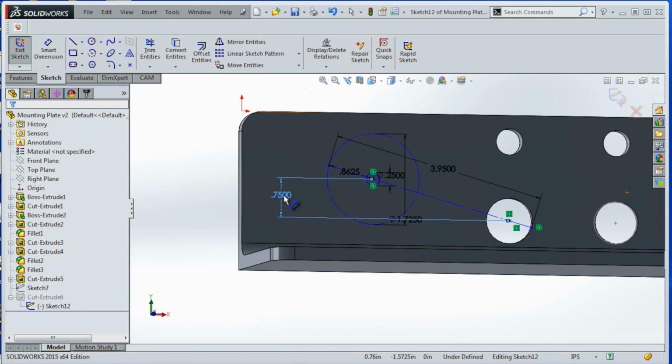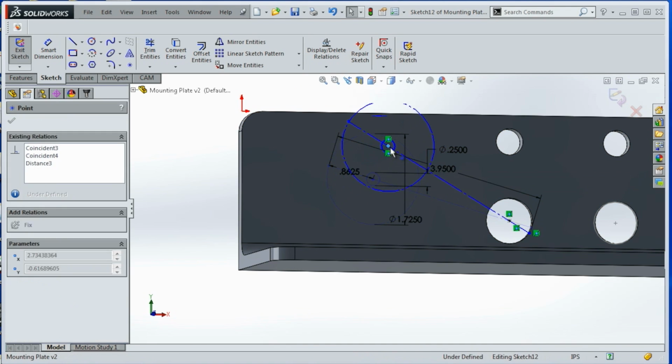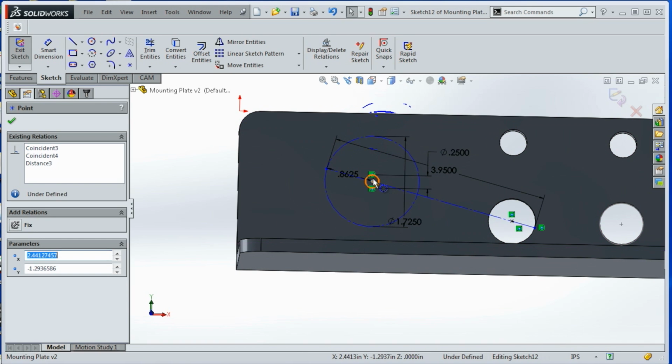So how easy is that, folks? Now if we take a look, again, you can delete these two dimensions, and you can drag this around, and anywhere you move it, that belt will have the correct tension. I think that's really cool. And again, the trick is the power in parametric CAD of using constraints on dimensions and constraints on geometry.